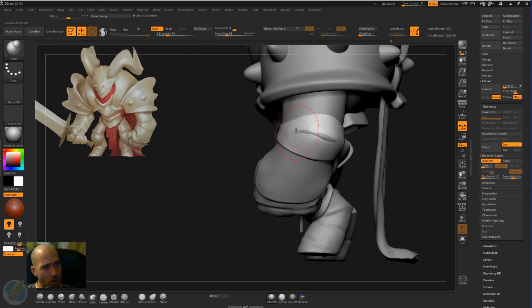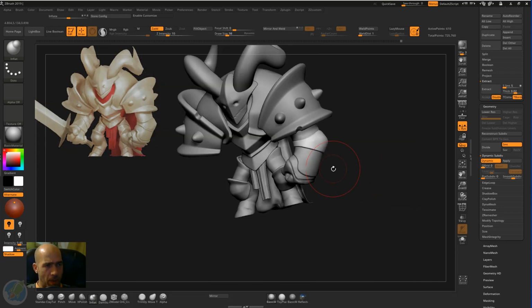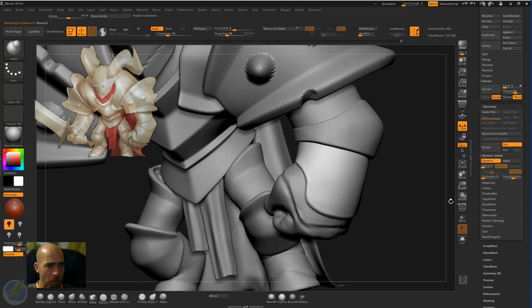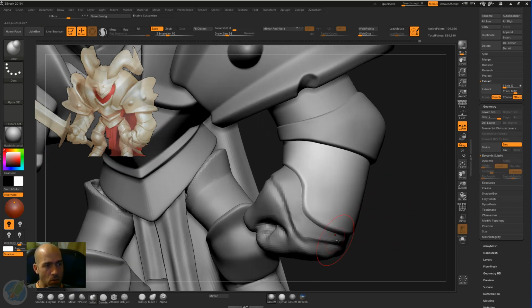Let's go with our inflate brush, inflate this uniformly, and it's fine. So now I will apply subdivisions in order to make this kind of groove. Apply here, the button, apply, next to dynamic, apply, and now we have 5 subdivision levels. How to groove? We can use Orb Cracks brush. It's pretty good brush for the grooves, but if you don't have this brush, we can use Dam Standard brush, which is 7 in our case here, and the Dam Standard brush is doing a good job.